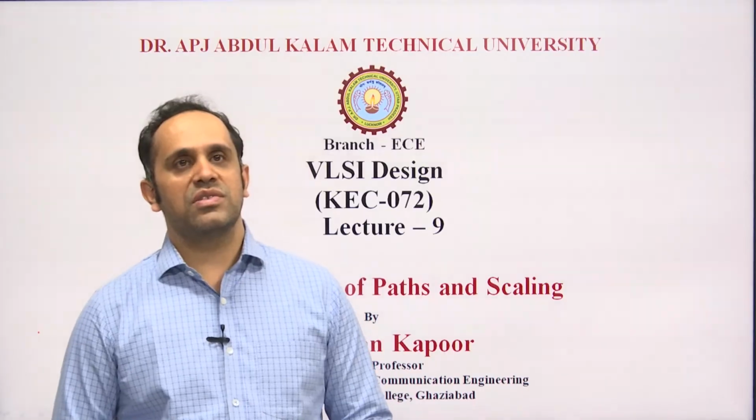We are going to continue from our previous lecture. In the last lecture, we discussed the linear delay model, which introduced us to the concept of logical effort, fan out and parasitic delay. Now, we want to extend that concept to different paths which might exist in a circuit. So, how do we calculate the logical effort in different paths and different stages, and also discuss something known as downscaling of VLSI circuits.